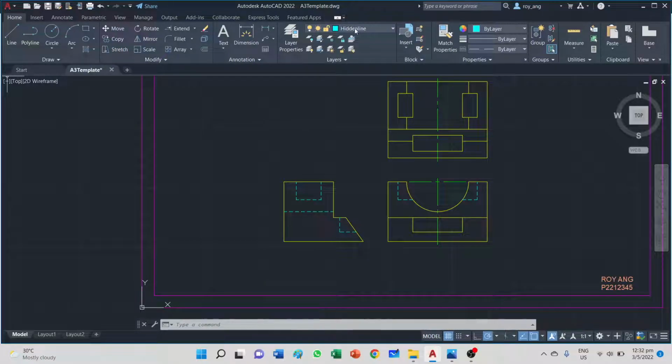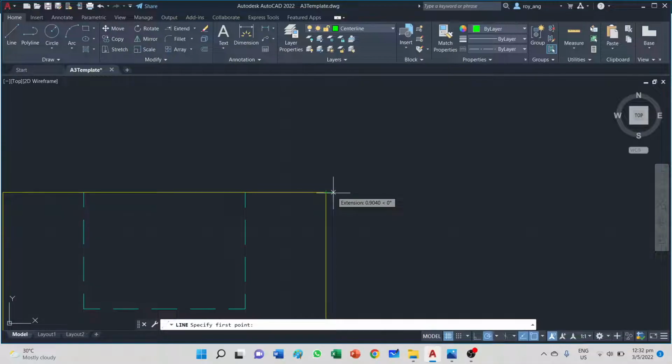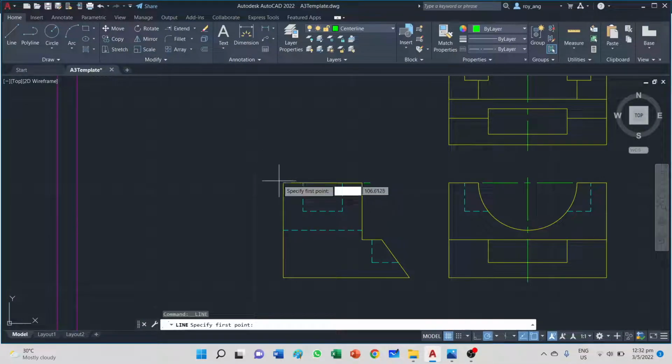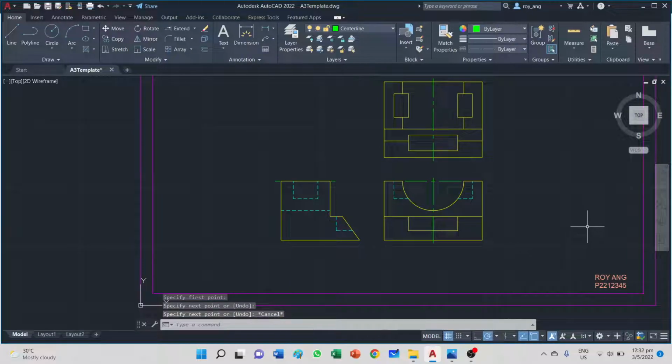But, however, there is some minor detail. There is actually a center line for the end view. And actually it's here. This center line depicts the curvature of the circle that was cut into the block, the R25. Okay, and that's what I have. The center line that runs for the R25 that is being cut across. Okay, with this, that's how you do figure 3 question 1c.